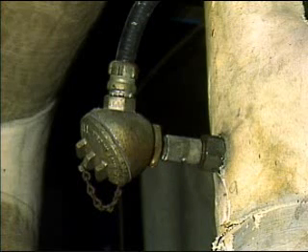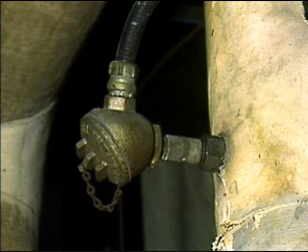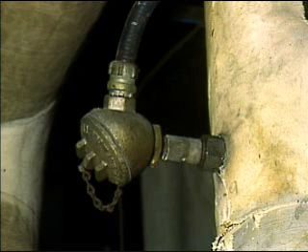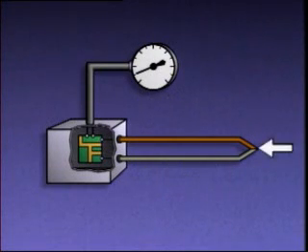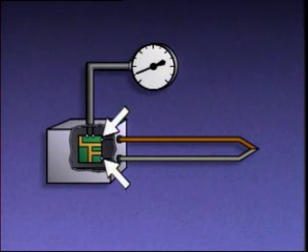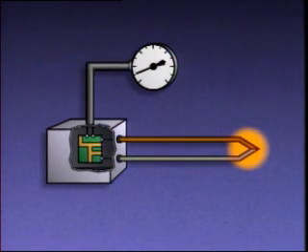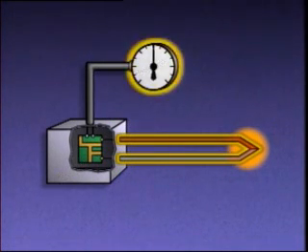While many temperature indicators are mechanical devices, some, like this thermocouple, are thermoelectric devices. They convert heat into electricity to measure temperature. A thermocouple consists of 2 wires of different metals joined at one end. The opposite ends of the wires are connected to an electronic circuit, which in turn is connected to an indicator. When heat is applied to the joined ends, a small voltage is generated in the wires. The electronic circuit detects the voltage and converts it to a corresponding temperature indication.